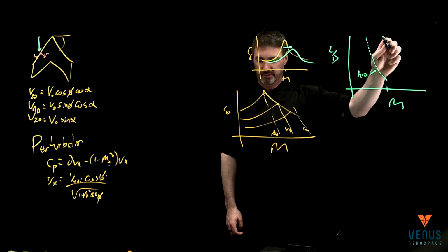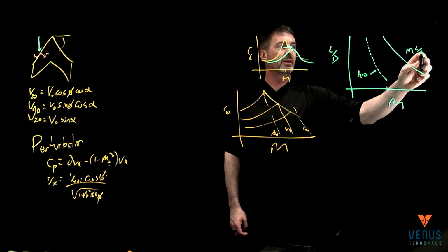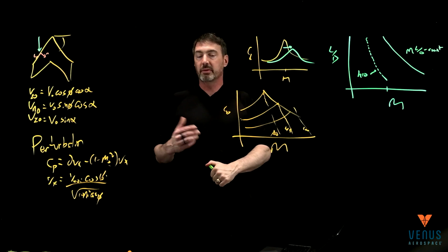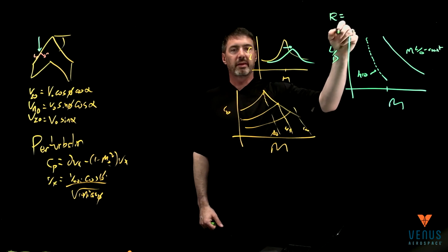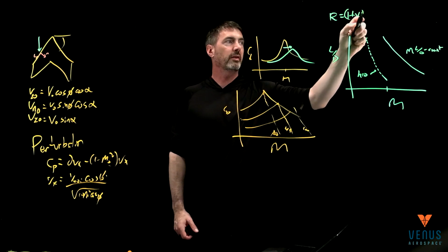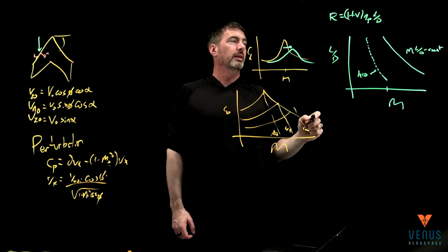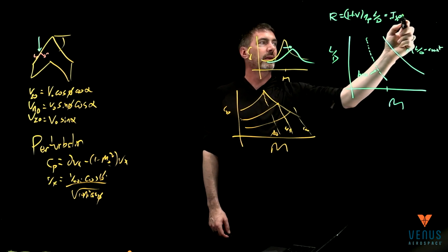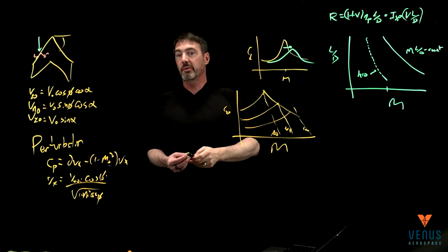And then there's a line here that sort of represents Mach where L over D is constant. Now, why am I drawing that line? Because in the end, you think of the range equation. You really should be thinking of it as heating value times propulsive efficiency times L over D. You can also think of that as Isp and then V L over D. So really it's grouping those two terms together.